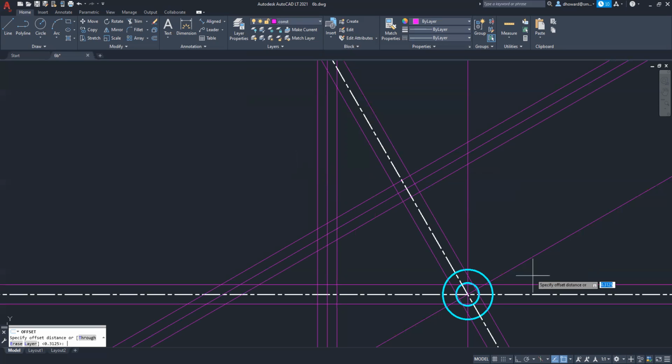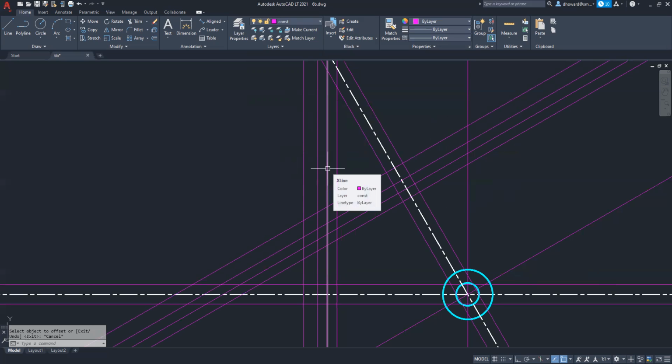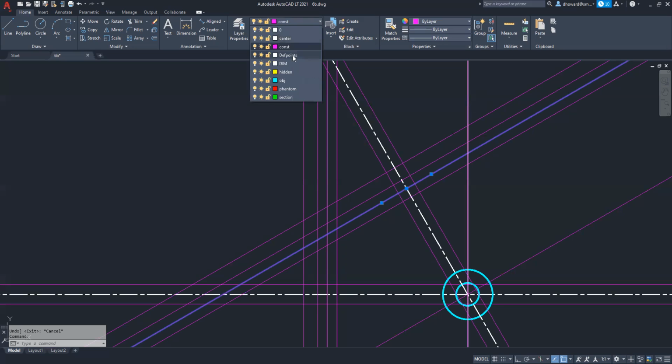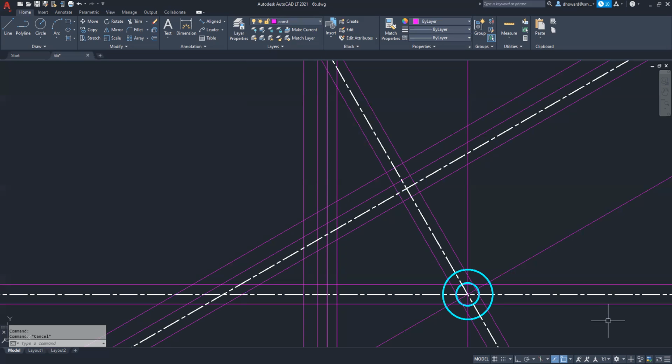And then we have the radius to offset, which is 25/30. So that is the outer radius. We'll bump that guy. Now again, I'm hitting the center middle line and then bumping it out. Okay. So to make that perfectly clear, that line right there is the center line, and I'll change it in just a second. In fact, I'm going to change this one right now. Make that center, just to show you what I'm talking about. It's the center of the hole going through this arm.